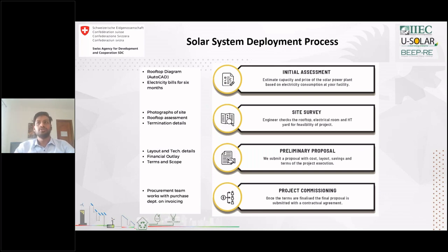And we are working on a rooftop system, so we'll have many safety installations that need to be done. We have to install proper walkways on sheet roofs where people and O&M teams can mobilize on the rooftops without damaging the sheet roofs, and we'll have safety lines where we can hook in. All these design aspects, and the earthing system, designated earthing for DC, AC and lightning arrestor position, need to be placed during the site survey.